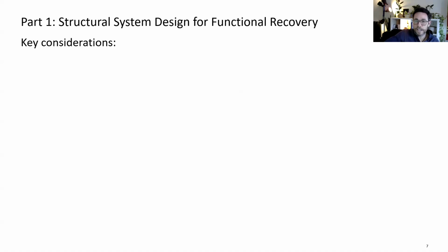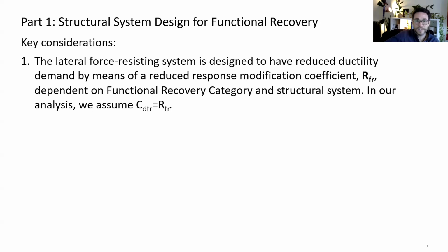So there are a couple key points that I want to share with you about our approach to developing prescriptive design requirements for structural system design. The first one is that the lateral force resisting system is designed to have reduced ductility demands, and this is achieved by means of a reduced response modification coefficient, this RFR term that I just alluded to. And that variable depends on the functional recovery category, and it's of course system specific, like the R value that we typically find in life safety design.